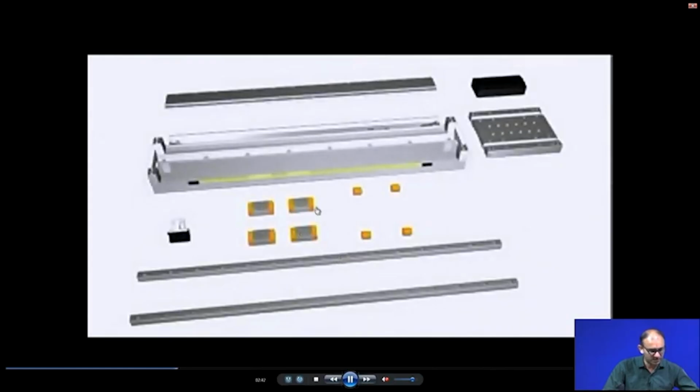So, these are the different components of the linear motor. This is called the forcer. The forcer is put on the top surface, the coil is wound around it, and this plate sits on top of the forcer, where you put any component. Suppose you want to move a workpiece, then put the workpiece here. If you want to move a tool, then mount the tool here.